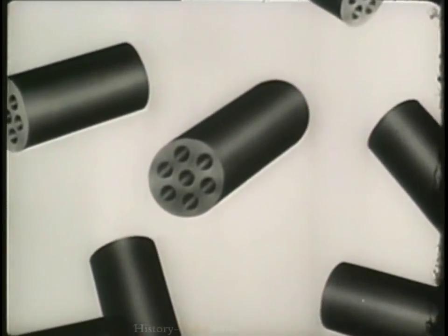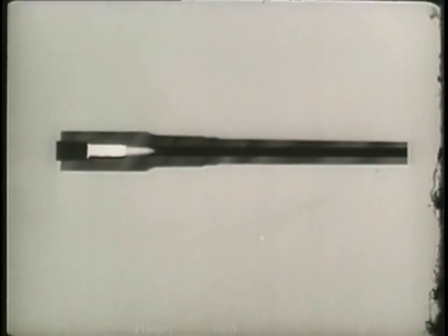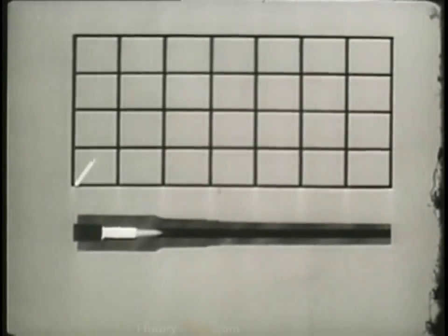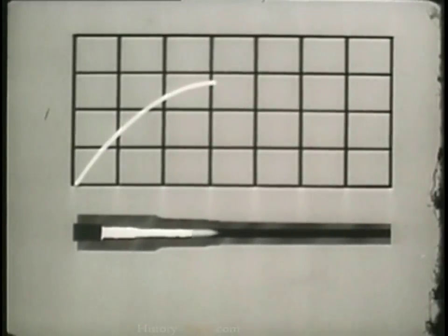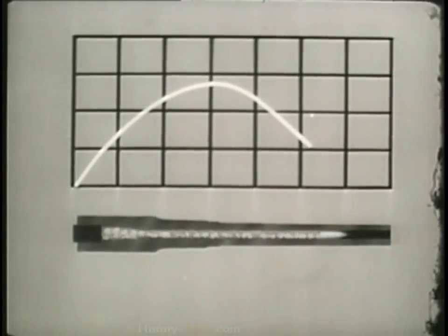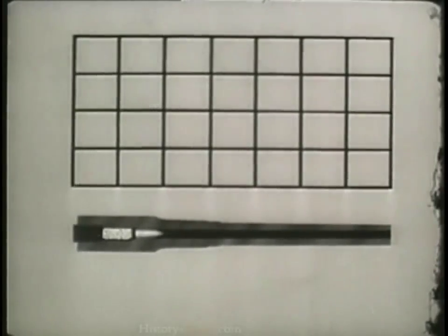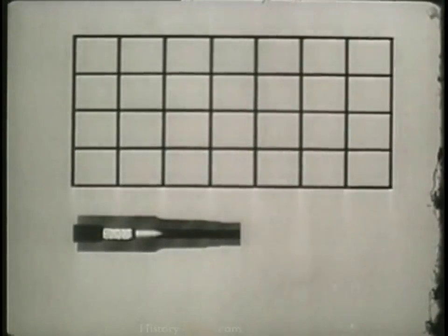When we burn a suitable charge of progressive grains, the pressure is moderate and sustained, sending the projectile out of the bore with a continuous push. This kind of pressure action is just what we need to get high velocity in long-barreled artillery. But now we'll see what happens when we use the same charge in a short-barreled weapon.